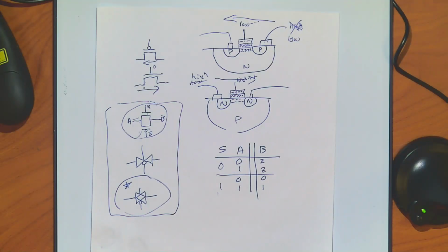Now, obviously, nothing is going to pass forever, right? The longer you go down a channel, the weaker a signal is going to get. So eventually, you're going to have to boost the signal. And that's just required by this. After so many stages, boosting it will be required. But you could just put in a simple buffer, right? Or you could switch to negative logic and just put an inverter, which is 2 transmission gates, and it'll be fully powered again, a new signal. So there's a couple ways we can do this. That can make it very easy. But ideally, this is going to power it. It'll be a little bit weaker, but not much. But it's now a nice, easy way to go.